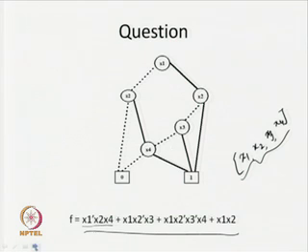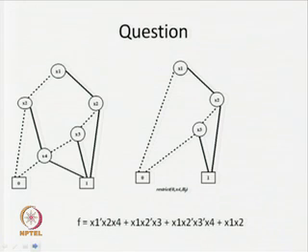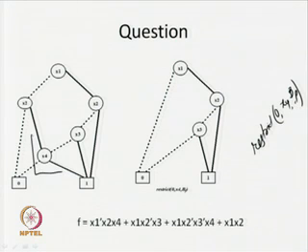Now, first we are saying that apply the restrict operation here, restrict 0 x4 of f. So, what is the rule? Since we are going to restrict this function on the variable x4, we are going to look for all x4 nodes and remove this x4 node from this BDD. When we remove this x4 node, its outgoing edges will also be removed.